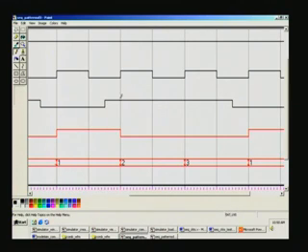So, if it is 1, what happens? From 1 to 2 it has gone. In 2, now again 0 1 1 0 bit pattern has been encountered, that is why at last 0 it goes 1 here. So, this is the corresponding output. So, whenever 0 1 1 0 and even in a recurring fashion you should have 1 here corresponding to that, and in state 2 we are analyzing, isn't it.